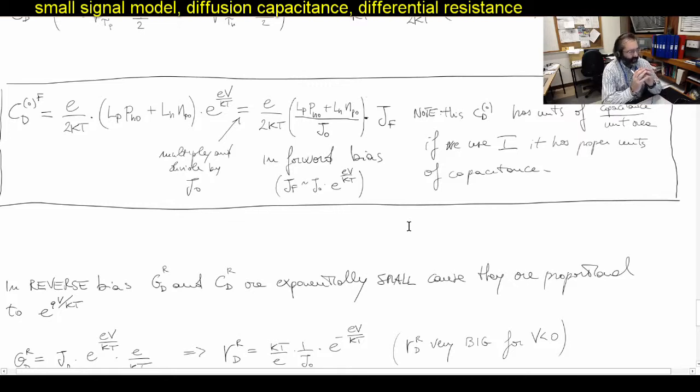What is important is to realize that the capacitances involved in the PN junctions are really cool, because they have this enormous dependence on the voltage, especially the diffusion capacitance. So they are effectively variable capacitances. And this is something that is really important in some applications. There are lots of applications where you may need a tunable capacitance.